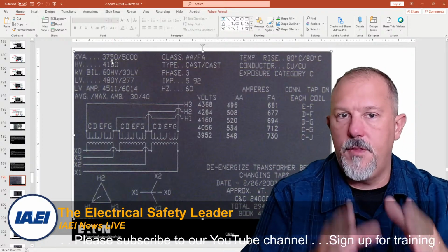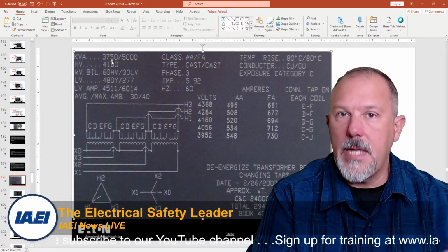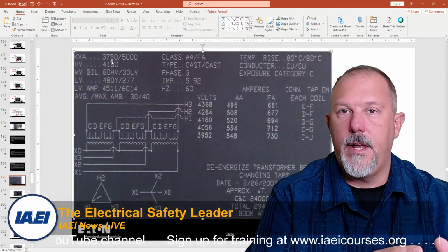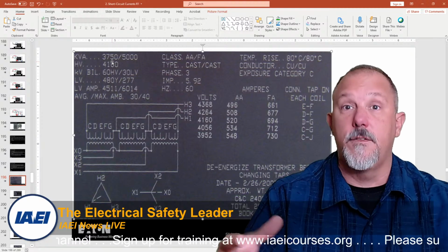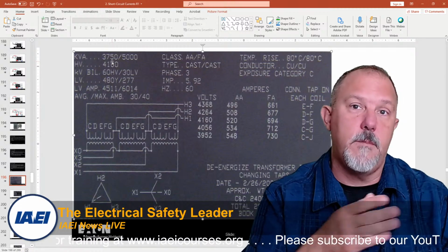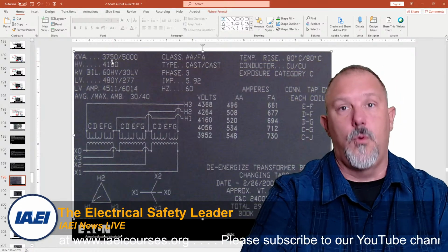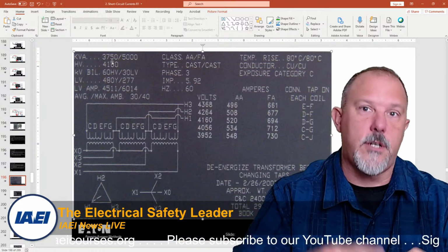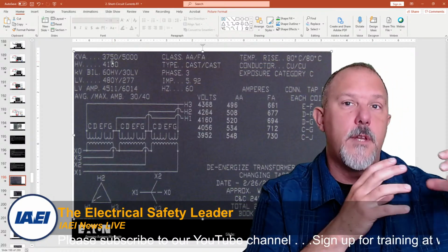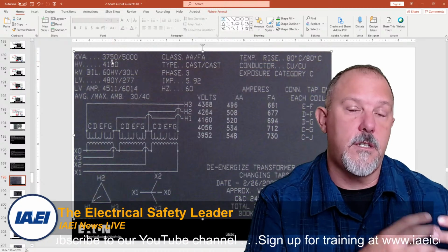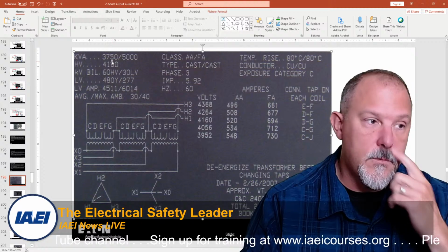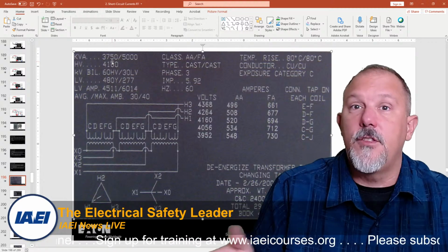But remember that the percent impedance is a value that is generated not because of the external cooling. That value is based upon the physics of the iron core and how we do the short circuit test and open circuit test and all that other good stuff, right? So we're establishing the key parameters for the performance of this equipment when a short circuit occurs, and you're passing through it.